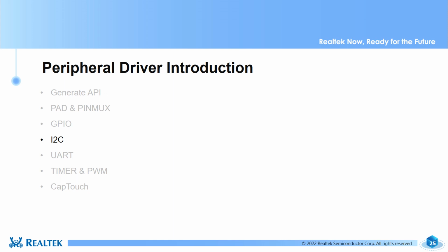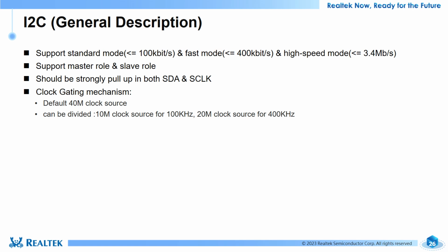Next, I will introduce I2C. I2C supports standard mode, fast mode and high-speed mode. Master mode and slave mode are supported. SDA and SCL need to be pulled up strongly.